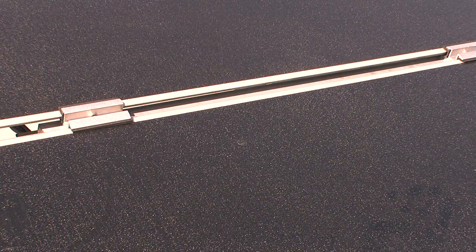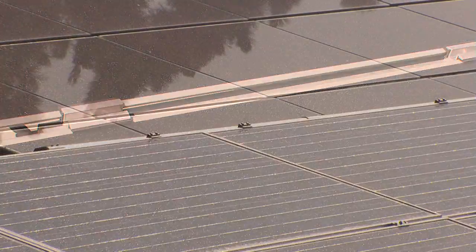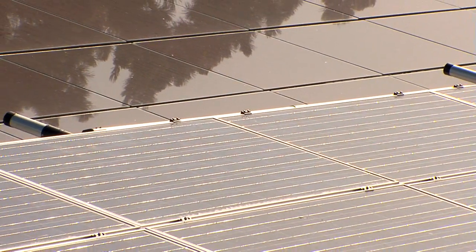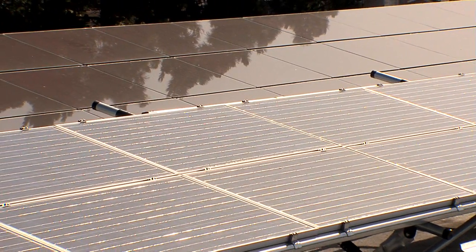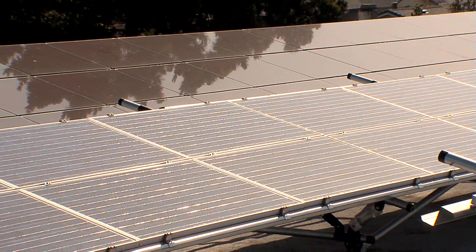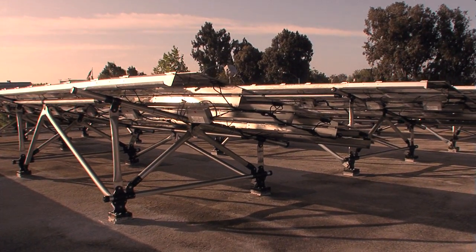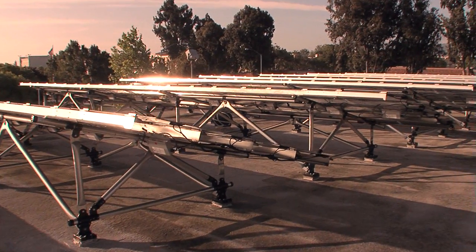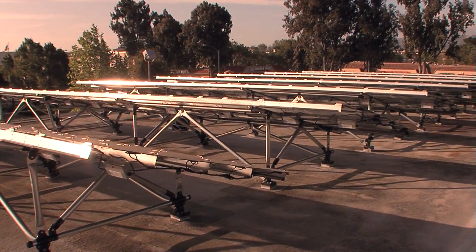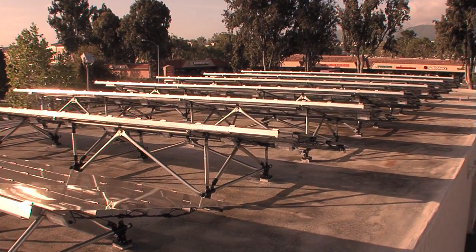The panels, as they get older, they may get dirty at different rates. They may have bird droppings. There's numerous ways that the panels can change. If you're limited to a series string, it's going to bring down your whole string. With the vBoost, it's only the modules that are connected to each vBoost. They're all modulated so they can maximize their output. That maximized output all goes back to the same inverter because it's all at the same voltage using the parallel nature of our wiring system.